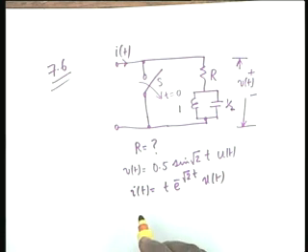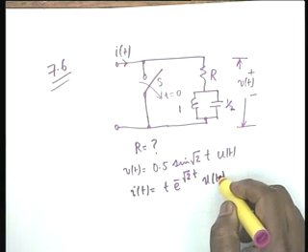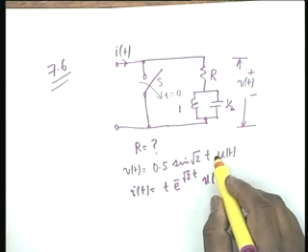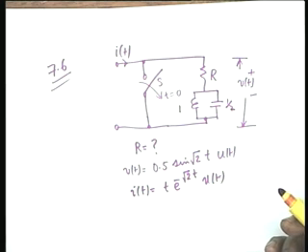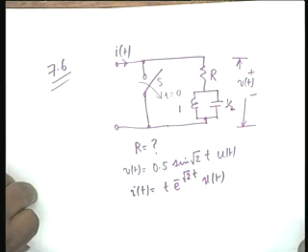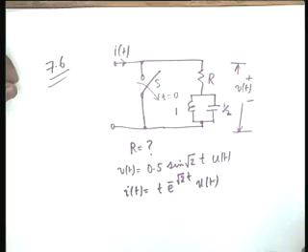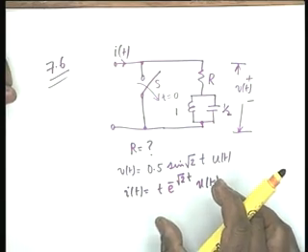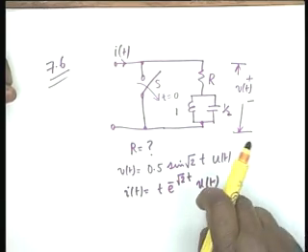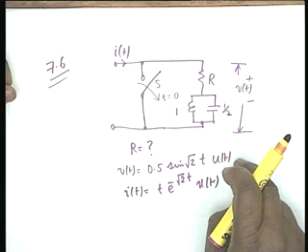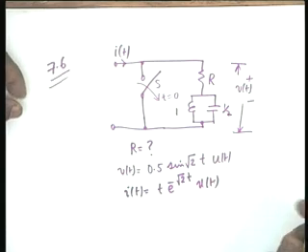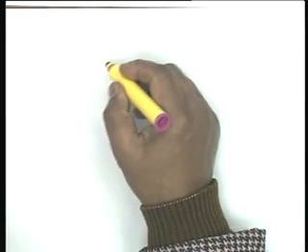Okay, this is the condition. V of t is found to be this, find out R. So, all you have to do is to multiply the current transform by the impedance and equate that to the transform of the voltage. Let us find out this a bit carefully.